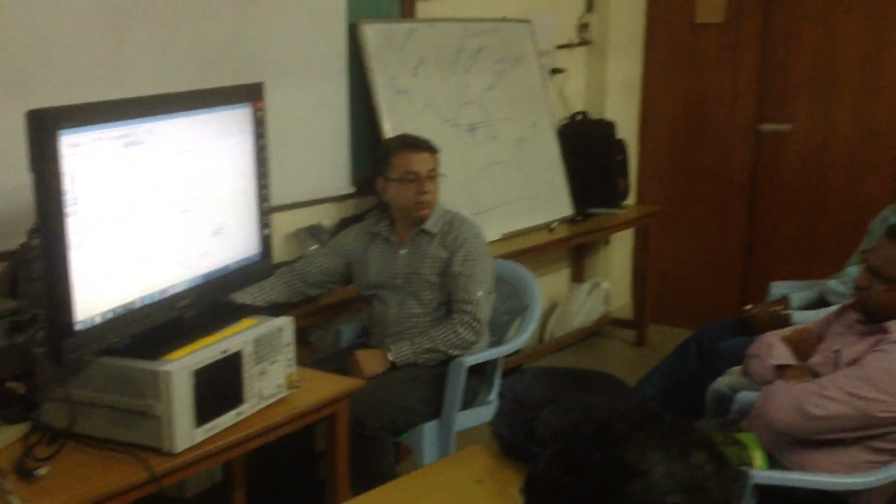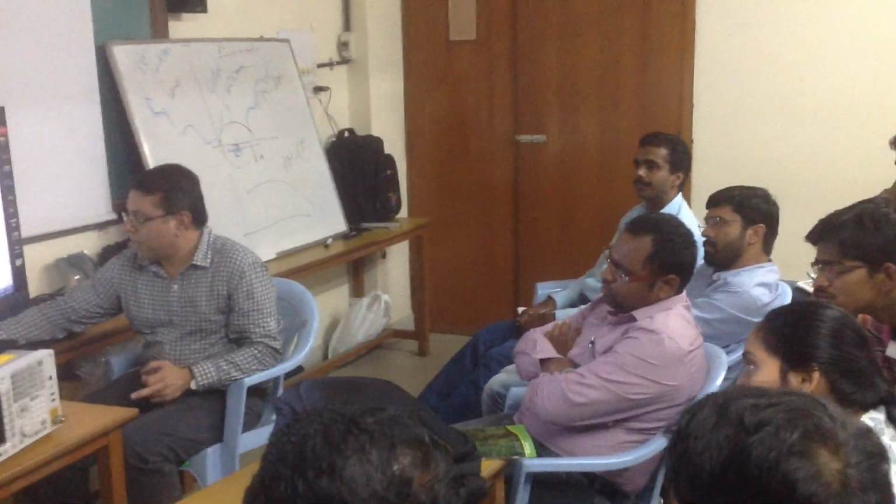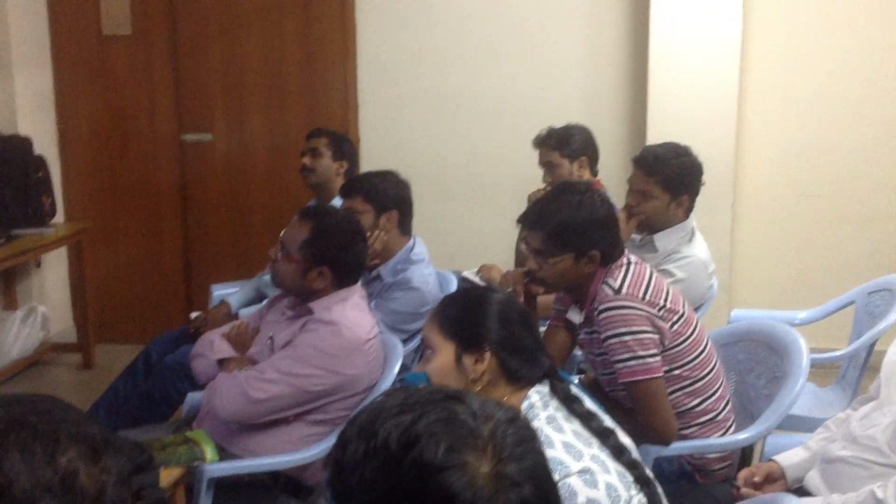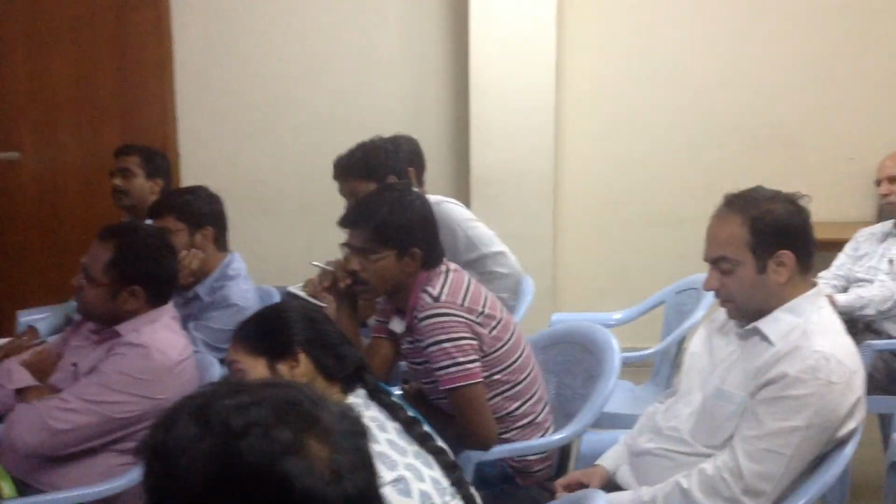It is 2.3 dB, 2.4 dB. Actually, when I match for the top tone, it was supposed to be 0.5 dB. But because I use a resistor at the input, the total noise figure has gone up to 2.4 dB. Now, what I do is I change this part.